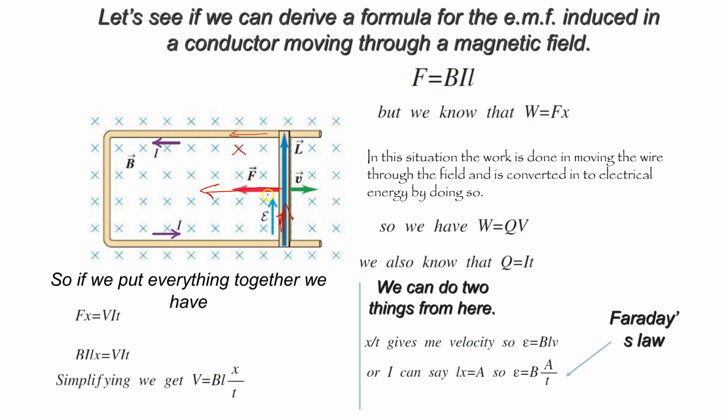So by thinking about this, the overall force is equal to B times I times L. And what we're doing here is deriving an equation for the EMF. We know from day one that E is equal to minus d of the magnetic flux over dt. We know that information already, but now we are dealing with this from a wire standpoint, that is, when a conductor is moving through a magnetic field. Whenever that is moving through a magnetic field, we definitely can determine where the EMF is going to be induced, or how it is going to flow in the wire, right?